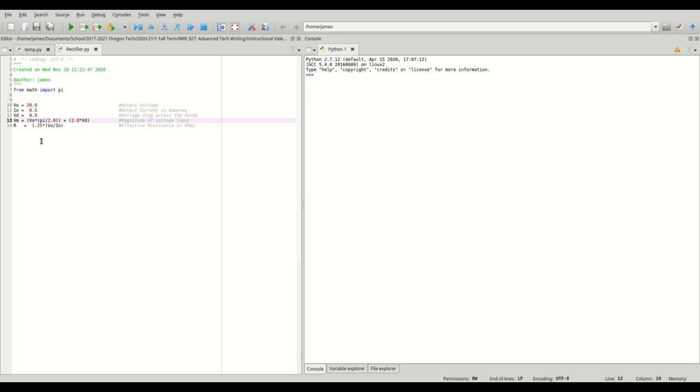But you can't forget to take into account the voltage drops across each diode. Remember, I said that only two diodes are conducting at any one time, which means you have two voltage drops between the input and the output. The LTspice model will require a resistance where the current won't exceed the rated maximum current. This can be calculated with Ohm's law, V equals IR, but in real engineering design, it's a good rule of thumb to add an extra 25% buffer to the resistance. Hence the expression 1.25 times V out over I out.